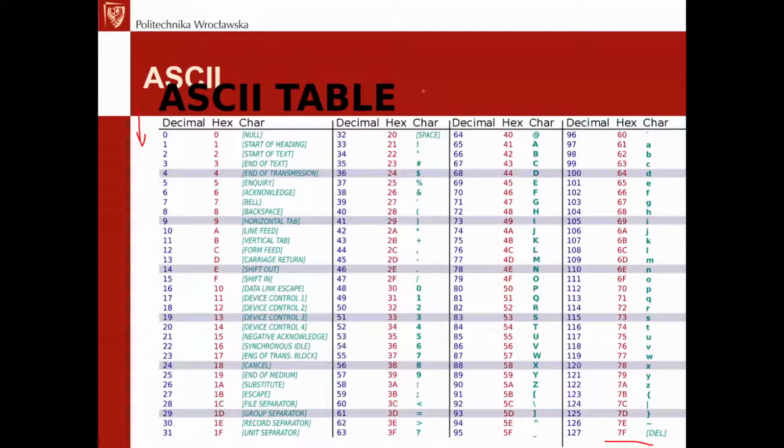So let's analyze the ASCII table, because it's a bit regular, and in the case of microcontrollers it's really worth knowing what's there. So what's the coding? We can split the table into a few areas. Area number one is from 00 to 31 decimal, which is 1F. These are the control symbols, various control symbols, like null. 0 is null. What a surprise.